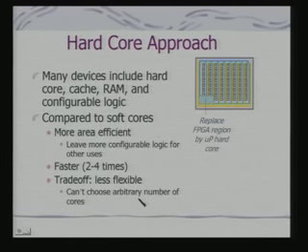In a soft core approach, I can actually choose multiple CPUs, and I might like to implement multiple CPUs depending on my requirements and map tasks onto these multiple CPUs. But those kinds of flexibilities are not really here, because here this CPU is expected to control the basic operations.